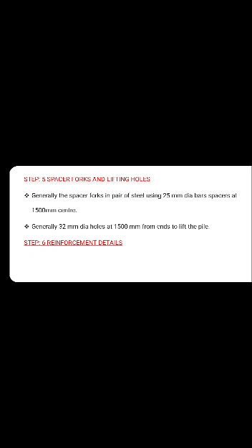As this is a precast pile, we have to lift the pile, place the pile, and install the pile. In order to do that, if we provide holes, it will be accessible. Generally, there is no exact specification of these holes. And you can see spacer forks also. Spacer forks are the cross sections to keep the steel in position. And in this section, 4 main reinforcement bars are provided. Inside that, helical reinforcement is provided. So these are the reinforcement details.